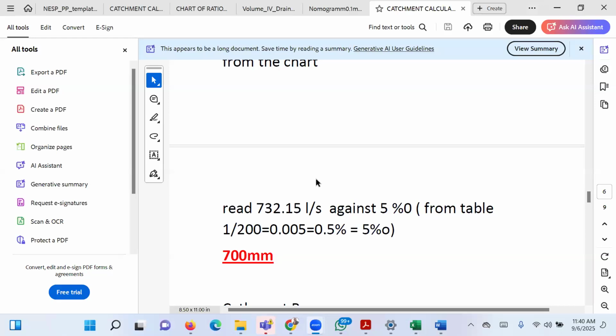My question here is, I'm looking at catchment A, and you have the length of pipe going across to the end of that catchment A. Yes. And that pipe is 700 mm, the diameter, and we've taken into cognizance the total contributing area in this section A to size it. So my question is, is the pipe going to be 700 from beginning till end, or will it change near the junction between A and B? It will be along the whole length, sir.